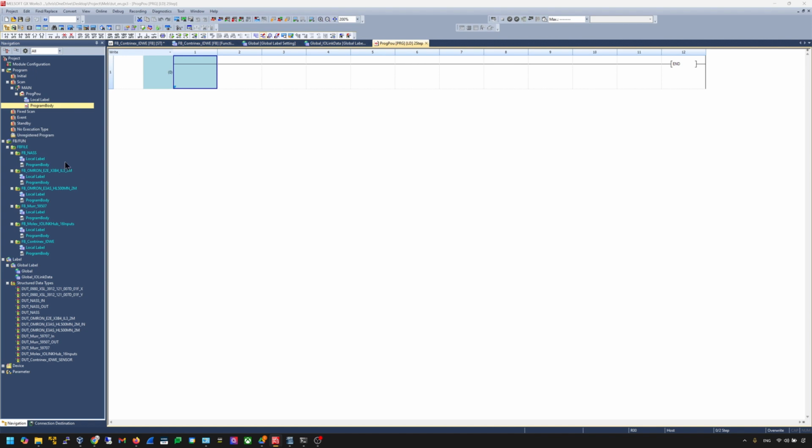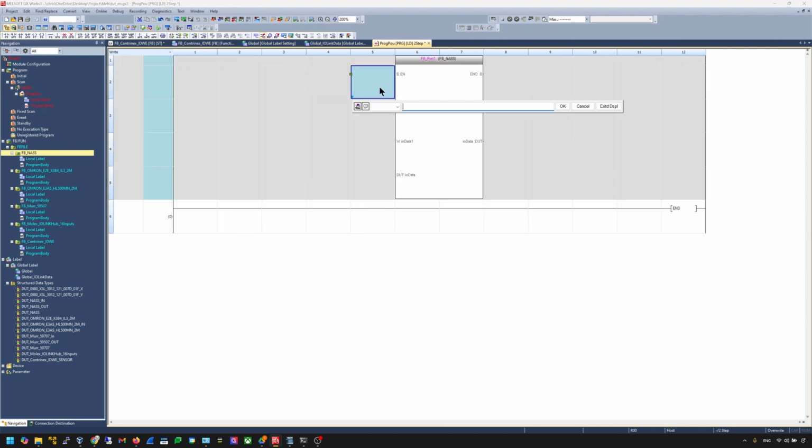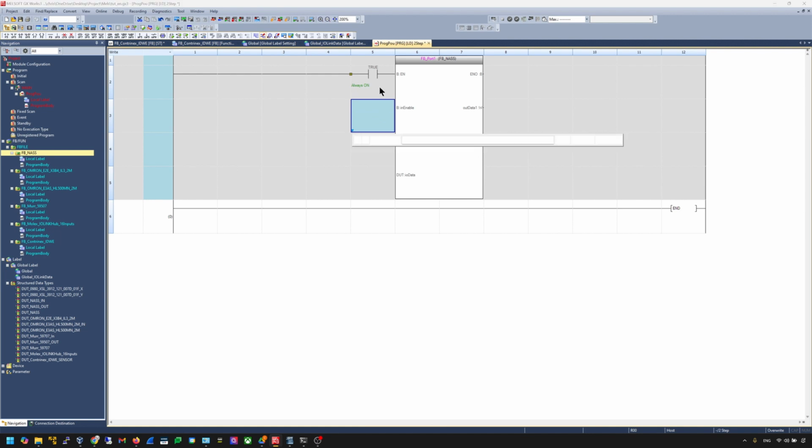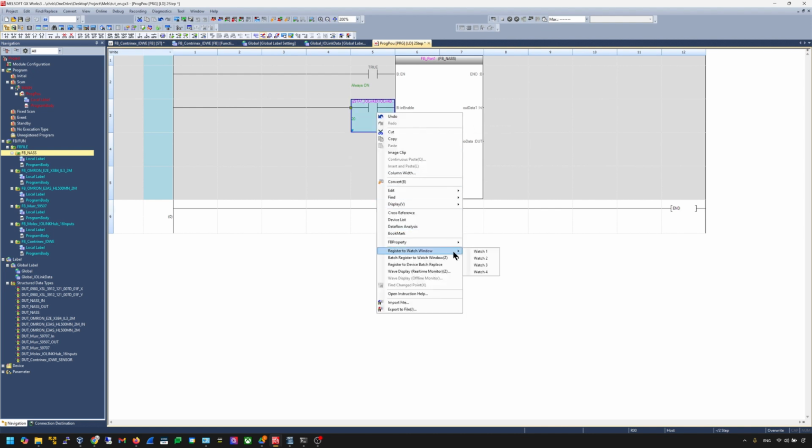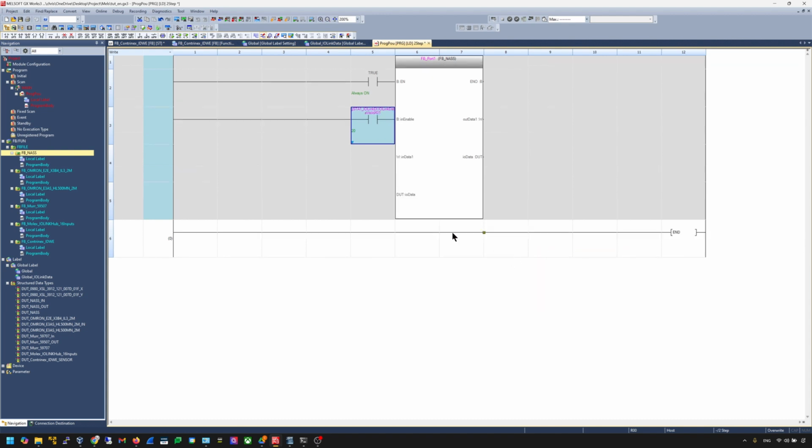For port 1, I'm using the smart connector. So go to here, drop it, and then FB port 1. For the EN, just put true in here. For the enable signal, I'll use GST1.DI in, and then you have a bit for you to check whether the communication of IO-Link works or not. This one, great. I would like to change the display a little bit to make it easier to see. It should be display, change format, yes.